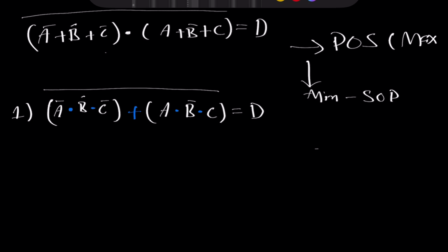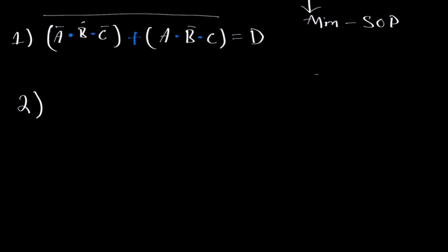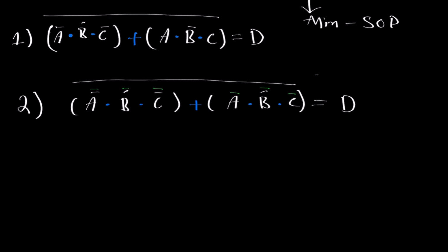gates to AND gates. Okay, step 2 is complementing each individual variable. That being said, we will have to add a short bar to each variable in step 2. We'll use a green color for step 2. Finishing up with step 2, everywhere you see a green bar, we complement each individual variable from step 1. Those green over bars on each individual variable are from step 2, because we complemented each variable.